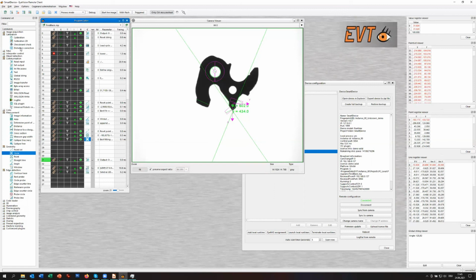The tool is here. Of course, this is an area tool. You will see if you use it on a smart camera with not so much computational power, it's not the fastest, but it's still here and it works. If you have a good lens, you can use the simple calibration tool, which does the simple scaling factor calibration, and it fits, and then you get real world coordinates for that. This is at the end exactly the same if you want to do robot vision, for example.